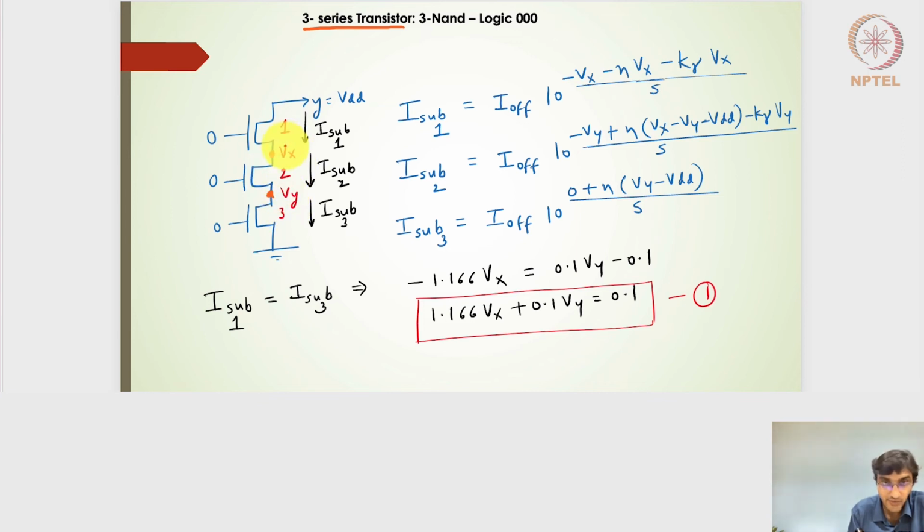If it is the other way, then there is some problem in our equation solving or in our assumptions. So in this case, what we have assumed is that through transistors 1, 2 and 3 there will be a current flowing. And thereby we identified Vx and Vy, and it turns out that the Vx potential is slightly higher than that of Vy, and our assumption of the subthreshold leakage current flowing from VDD to ground makes sense,